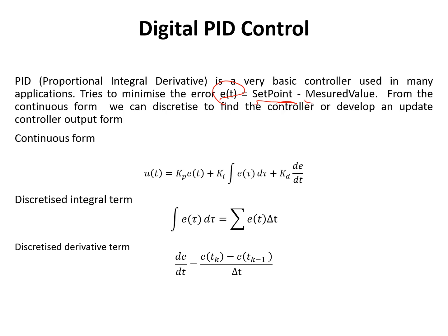And then we actually measure the output using some sort of sensor. For example, again, in the pressure control, we would measure the pressure using a pressure sensor. And in the cruise control, we can either measure it using wheel speed sensors or GPS. However, wheel speed sensors will still work when you're underneath in a tunnel where there's no GPS reception. So that's generally the norm to use wheel speed sensors. So we have a set point and a measured quantity, and the difference between this is termed the error. And then using this error, we can get the individual terms of the PID controller, and the total output is simply the summation of those three.